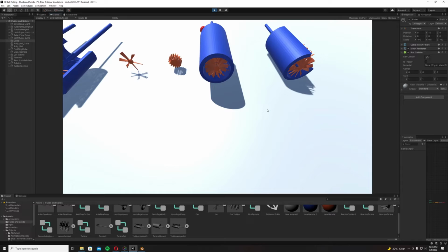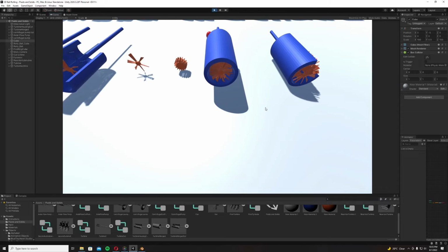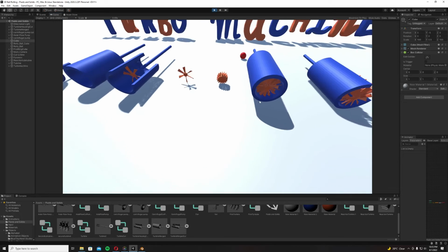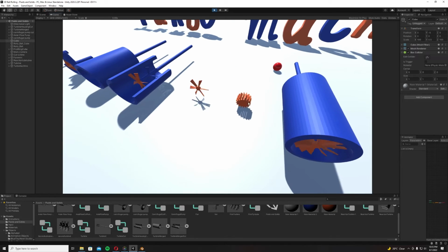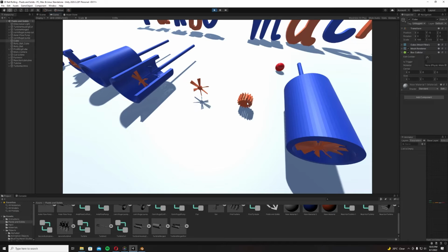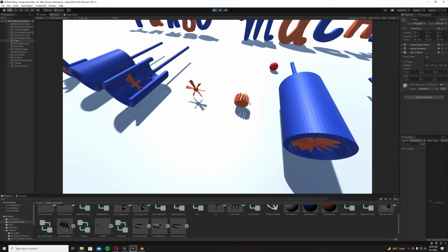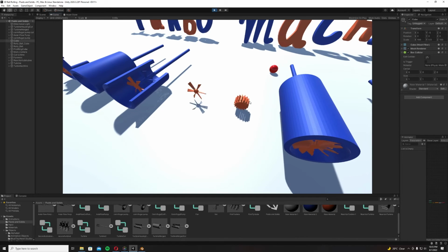Impulse turbines specifically use kinetic energy from the spinning turbine blade to generate electricity. The impulse turbine is these blades on the left right here. The blades are referred to as buckets, and as the fluid flows and hits the buckets, it will spin the turbine blades. The fluid, when it comes in contact with the blades, has a relatively constant pressure and velocity, and the blade designs are pretty symmetrical.